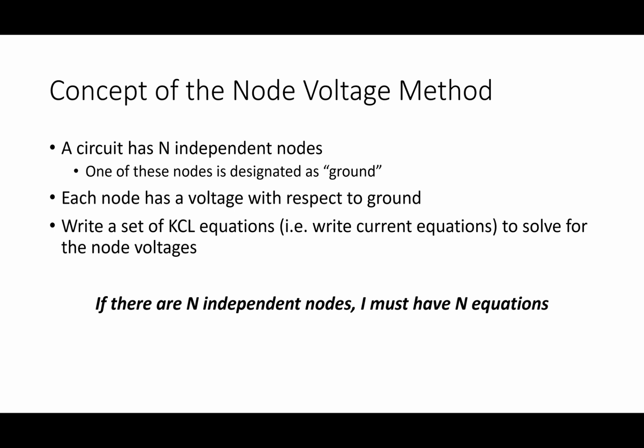You guys got to be really careful when you do this and make sure that when you look at your equations, they better all be currents. All right, unless I have a supernode, in which case there's going to be something that relates voltages. But check the units on these things. I see all the time, especially when I give supernodes, I see amps minus amps equals volts, right? Equations that don't make sense. So we're going to talk a little bit more about that.